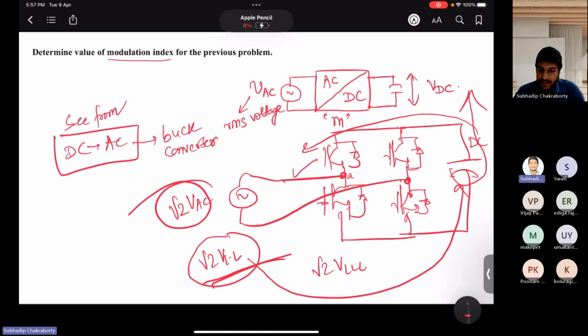So the DC link concept is very important. If your DC link voltage is maintained above the minimum required threshold, then you can form lower levels of AC amplitude voltage, √2 V line to line, like this example. But can anyone tell me, what if I maintain a DC link voltage lower than √2 V line to line?